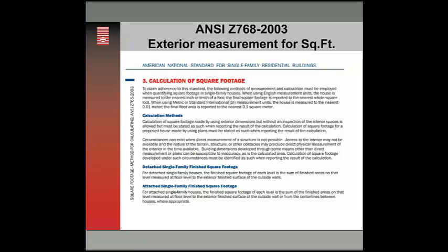So if you're going out doing this testing nowadays, if someone puts in a request and they haven't submitted that information to the code officials at plan review, a good step to take is, in the first conversation, to ask: do we have volume numbers for the blower door test?